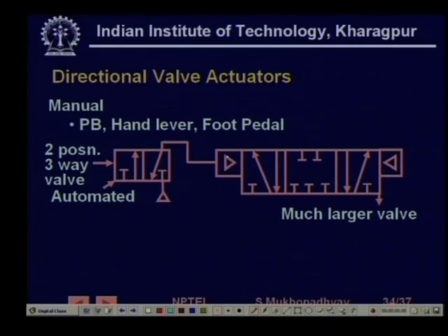So, this is a large valve. To be able to shift that position, you see pneumatic pilots are used. So, this is a pneumatic pilot, which is used to shift this main valve, right. This may be a big hydraulic valve also, and this hollow triangle indicates pneumatics.